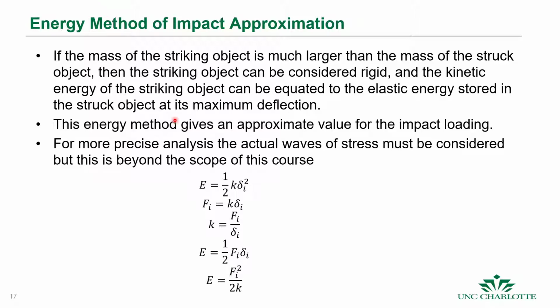Okay, and we can use this if the mass of the striking object is much larger than the mass of the struck object, sort of in the case of a hammer hitting a nail. Then we can consider that the striking object is big and rigid, and that the kinetic energy of that striking object will be related to the elastic energy stored in the struck object at its maximum deflection.